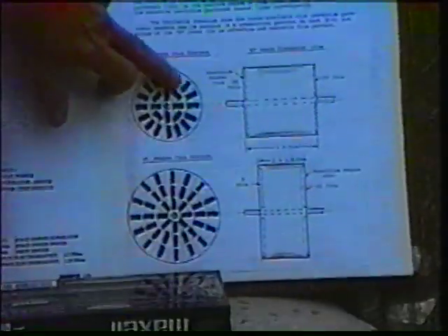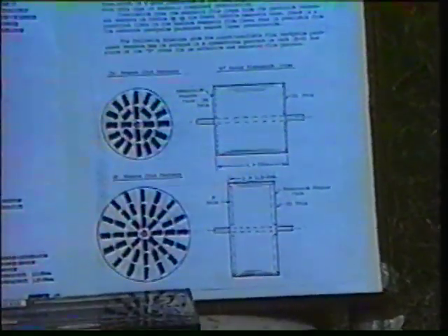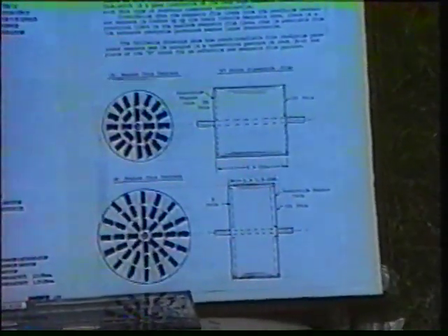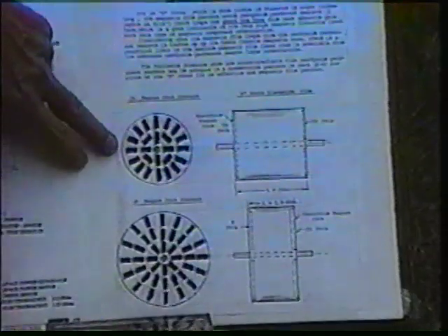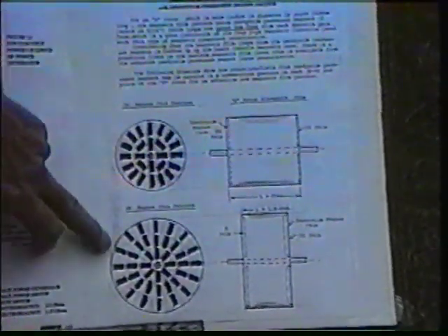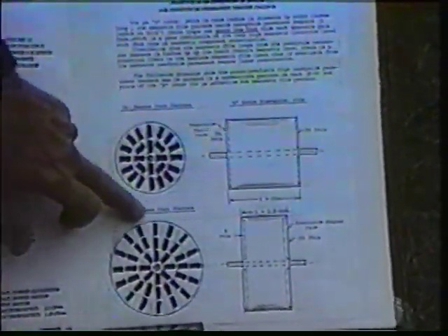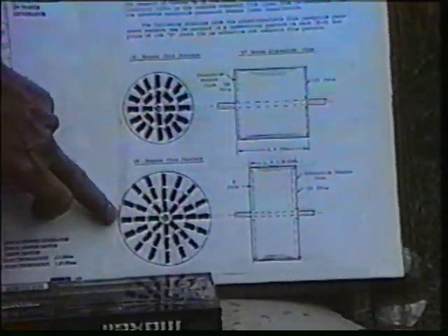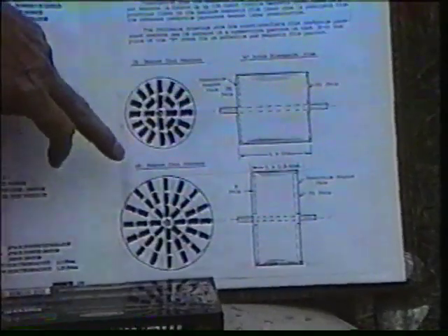In this specific rotor, I have 24 neodymium magnets on either side. Of course, one face is North Pole, and the opposite face is South Pole, but in this specific pattern. This is just to illustrate that you can have an increasing number of magnets. This particular one has 40, but there's essentially no limit to the pattern.